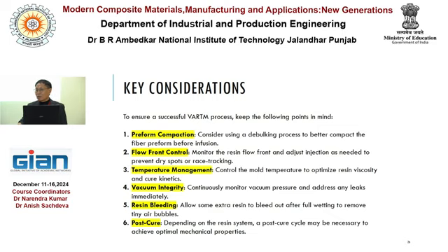And that buckling mostly can be recovered after removal of that compaction pressure, but during buckling, it can leave permanent breakage in fibers. So it will be a micro defect after manufacturing as it is. So don't neglect the optimal compaction pressure.